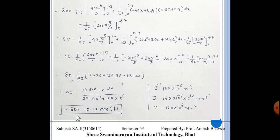So finally we will get delta D as 10.47 mm downward at point D. So whenever we have this kind of simply supported beam and we want to find the deflection, at that time we have to find the reactions in the form of P.